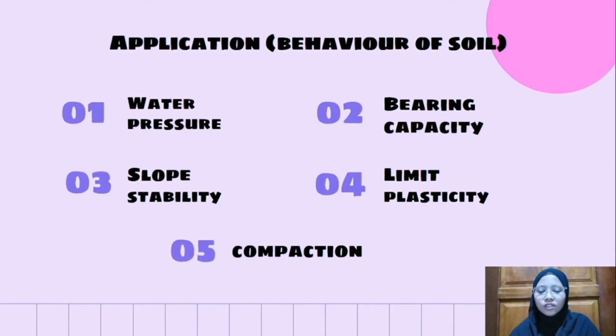Firstly, the strength of soil is affected by water pressure. When the soil is too wet, the strength of soil will decrease because friction between two particles will reduce and the water pressure is high. The cohesiveness of soil will decrease when water content rises.